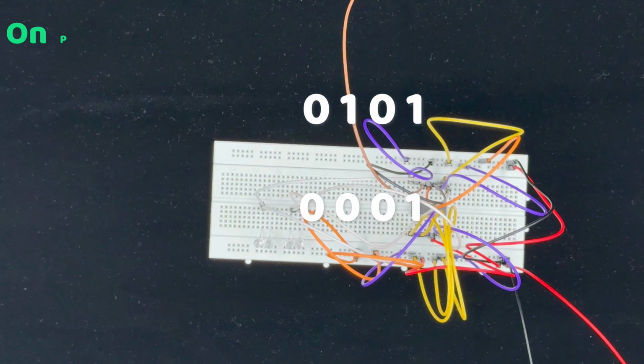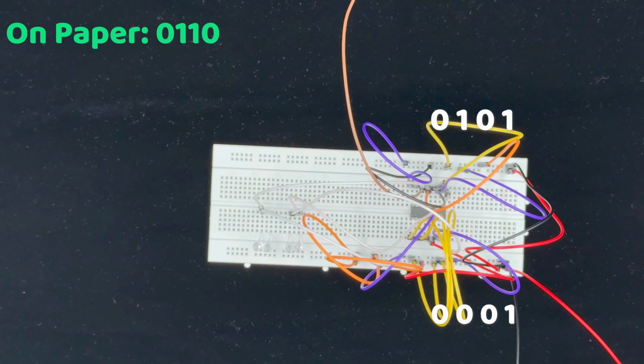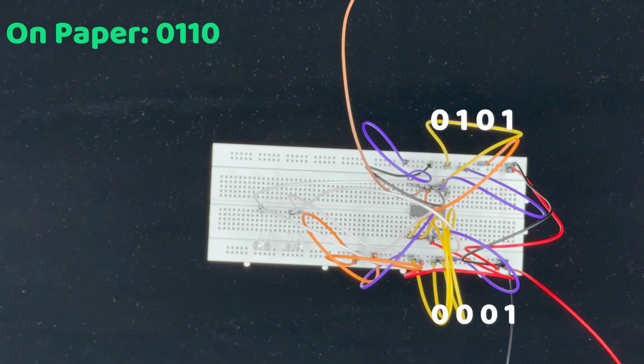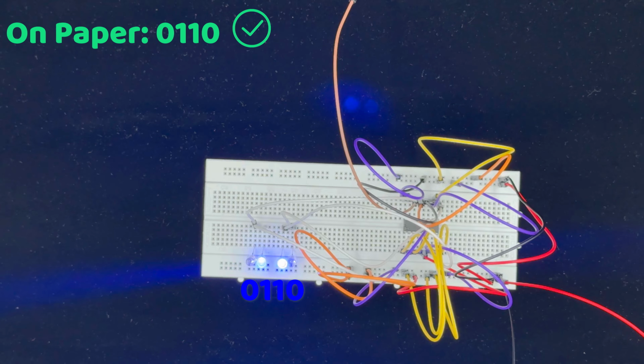I represented those two numbers in our circuit as inputs to the adder and connected these 4 LEDs to the output or summation pins of it. When we power our circuit up, we get the 2 LEDs in the middle lit up. Mind you, in the circuit, a lit up LED is a 1 and an off LED is a 0. So our result here is basically 0110, which matches our result on paper. Bingo. Let's take a step further though.